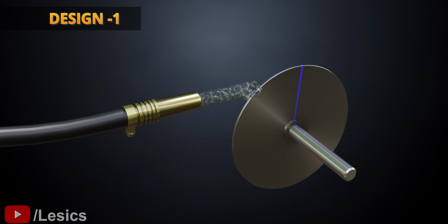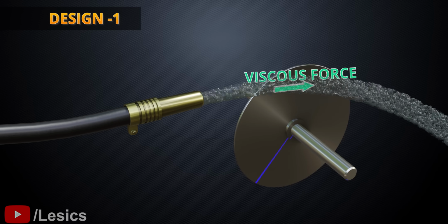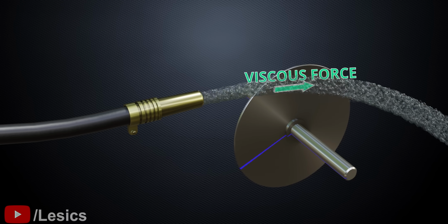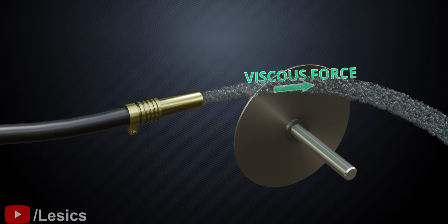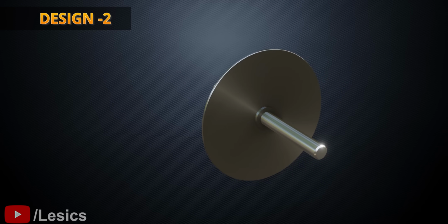If you produce the viscous force tangential to a disk, it will start to spin. Hooray! You've produced the simplest form of Tesla turbine. However, this is quite an inefficient turbine. Most of the jet's energy is lost here. Let's make this design more efficient and practical.